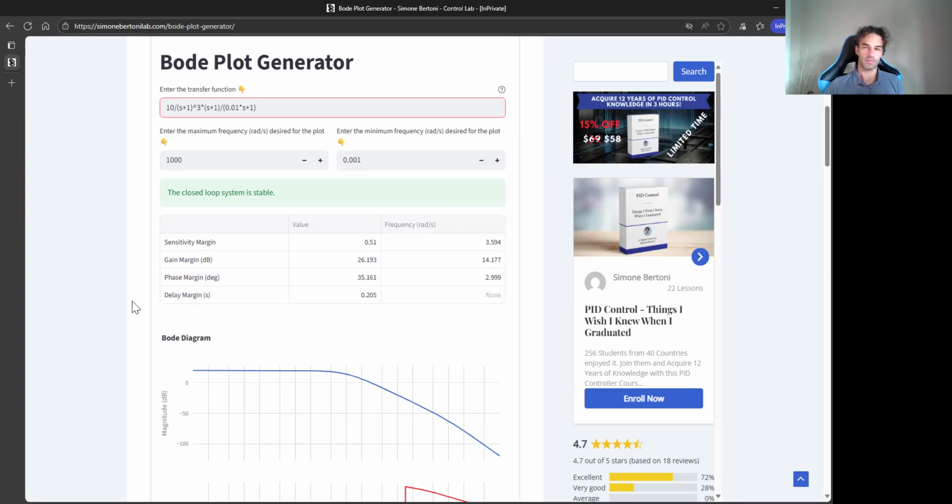But what it's telling us is if you have a communication delay, for example, in your loop, you might have a controller that is reading a temperature, a distance, whatever you're controlling, at a certain point and is passing it on. It's controlling the actuator half a second later, because of your program, because of your loop, whatever.